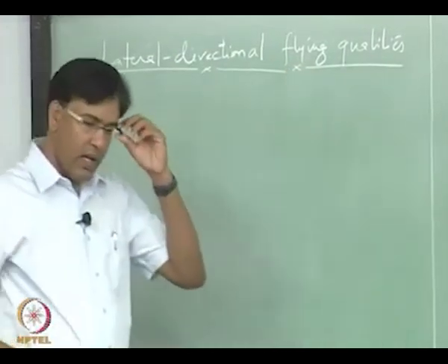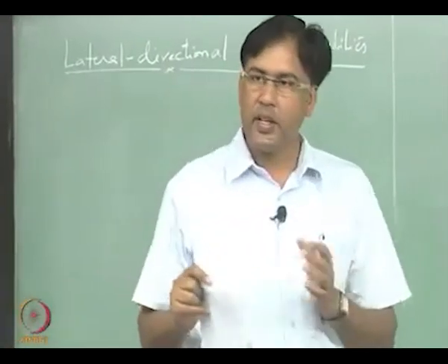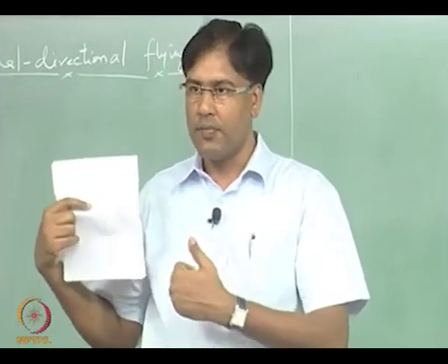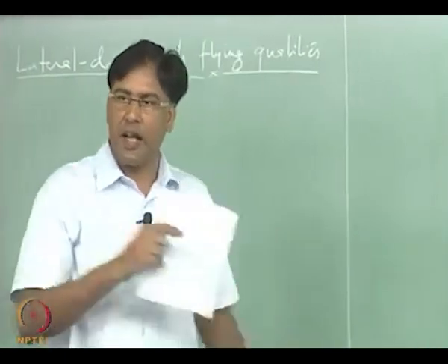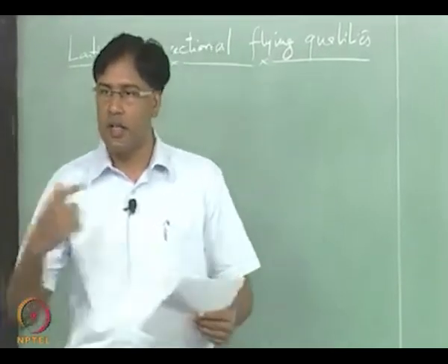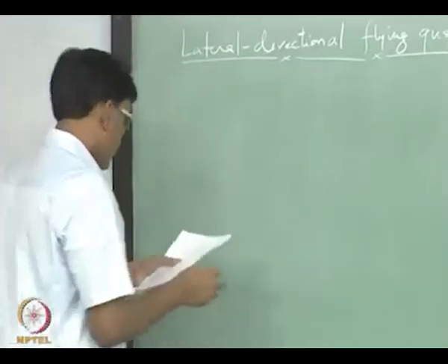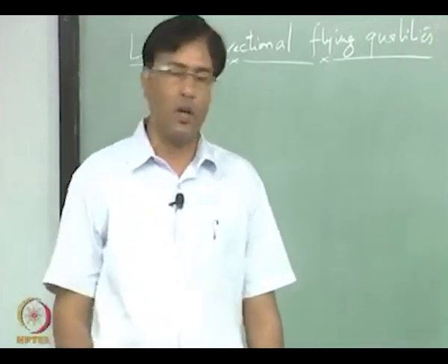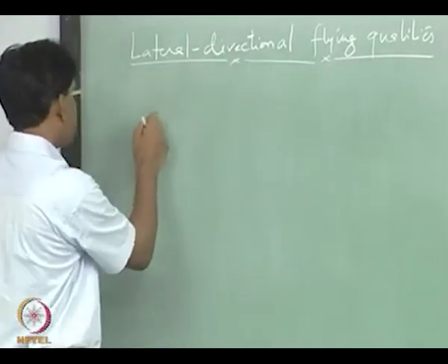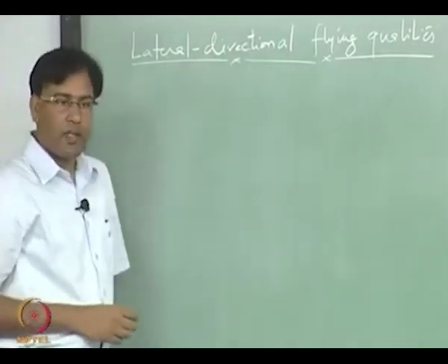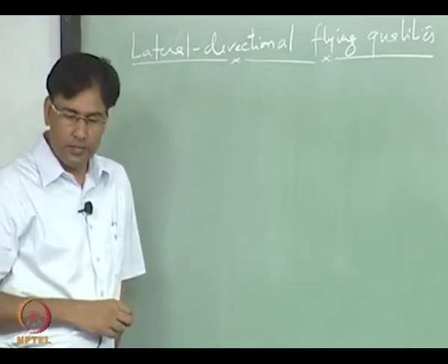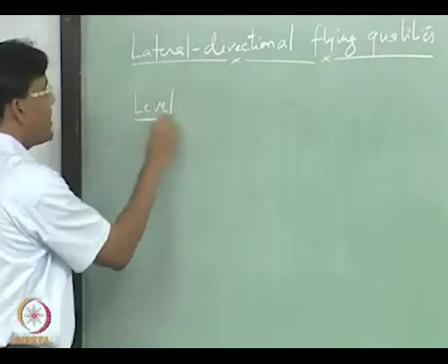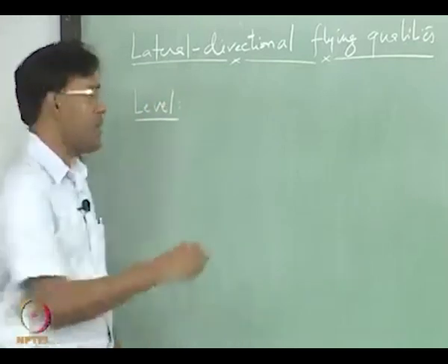These qualities are actually not specific to an operating condition. In general, any flying condition, if your characteristic parameters are lying within limits, then you can say that the aircraft is good for flying and handling both. Handling is in terms of the load on the pilot, right, workload. So, we had three categories in which we classified the dynamic behavior of the aircraft, and one was level. Level was related to the pilot workload, right.